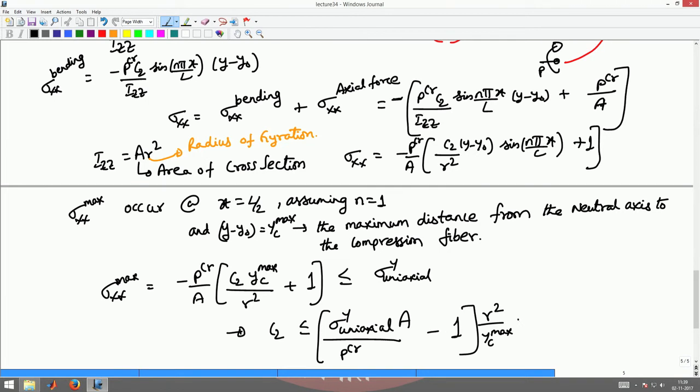Commonly it is attributed that material failure is different from stability failure, in the sense that it is independent of the material yield stress value, but the material yield stress value governs the maximum deflection you can have. It is not independent of the material failure. Because of the geometry, the structure continues to deform, because you are writing the equilibrium equation in the deformed shape. It has multiple solutions possible at a particular stress value, and that causes the stress to exceed a limiting value given by a material failure limit. It is not that stability induced failures are not material failures.